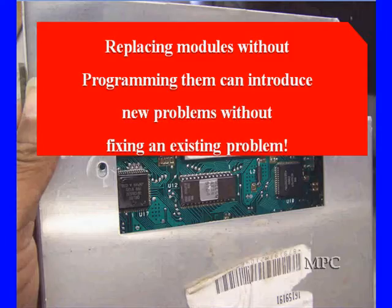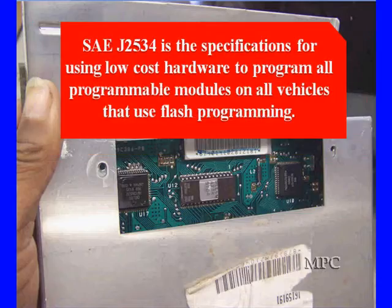I can't tell you the number of times we've gone out on communications problems to find out, well, I had a code, so I stuck a new module in. It was a GEM module on a Ford. Well, did you reprogram or flash program the GEM? No. Well, you know what GEM stands for? GEM stands for Generic Electronic Module. It is generic. Its personality is adjusted to the vehicle.